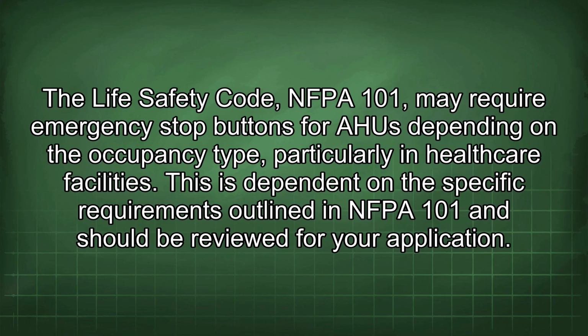The Life Safety Code, NFPA 101, may require emergency stop buttons for AHU depending on the occupancy type, particularly in healthcare facilities. This is dependent on the specific requirements outlined in NFPA 101 and should be reviewed for your application.